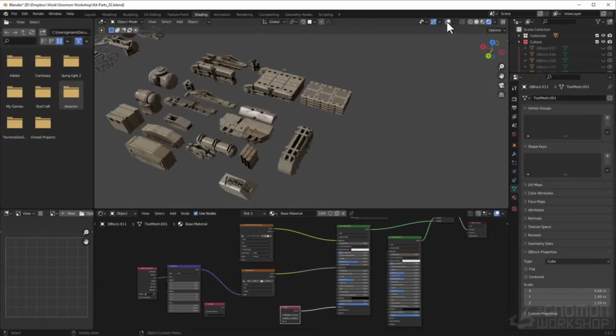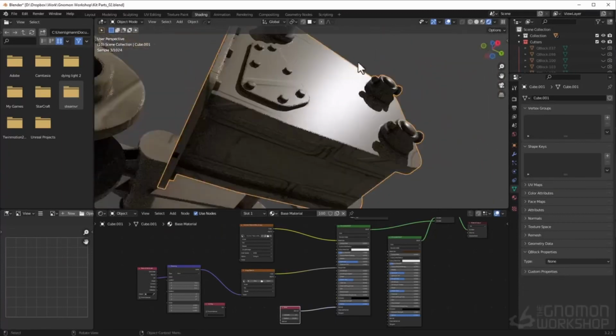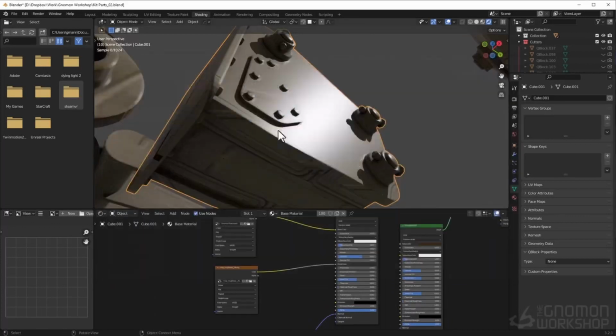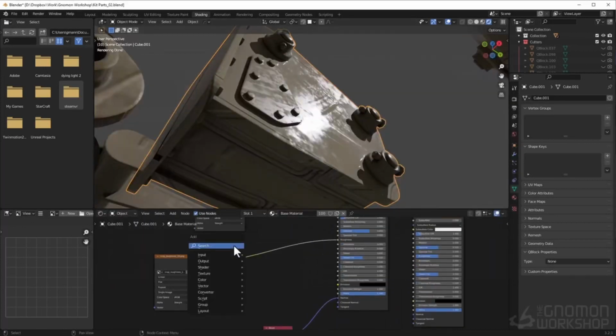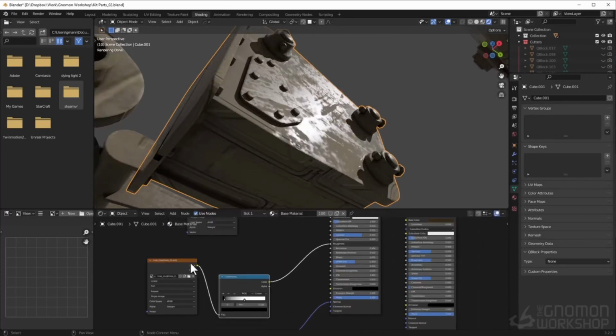It's all looking a bit too smooth, so I find an angle where a piece hits the light nicely, and then I'm going to add some roughness to the surface. I added my image texture node with the roughness map I got from my texture library, and added a color ramp in between for control. I'm playing around with that a bit here. I've already got UVs set up because of the base color I did, so no need to worry about that.